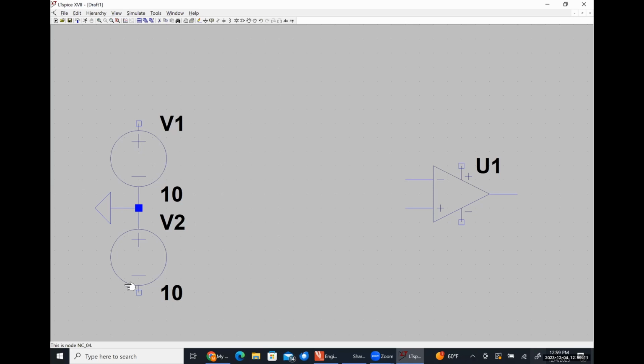Okay. All right, so one thing that I want to show you guys, I'm going to put this label as VCC plus. I'm going to put it up here. So this node is now VCC plus, and then I'm also going to drop that label over here on the positive power supply terminal by the op amp.